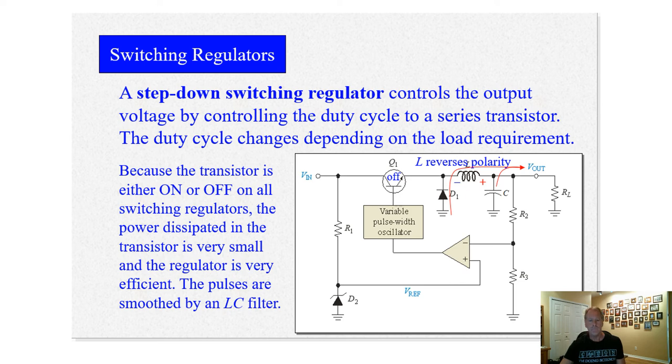So on a circuit board, for example, you have a main switching regulator coming in, and then that would distribute an intermediate voltage rail to the rest of your circuit, and different parts of your circuit, like your Ethernet circuit maybe, or your microprocessor, or maybe some audio circuits, they would have separate series regulators to handle their voltage and current needs. But anyway, this is a step-down switching regulator, super common.